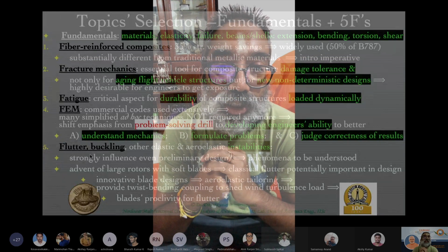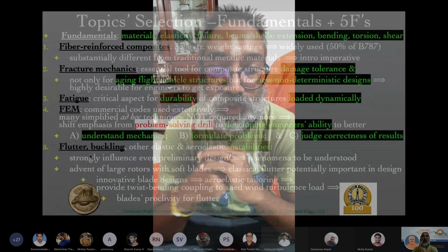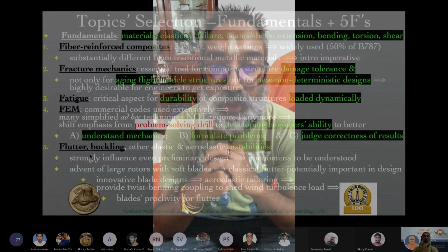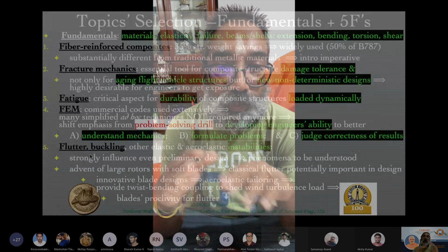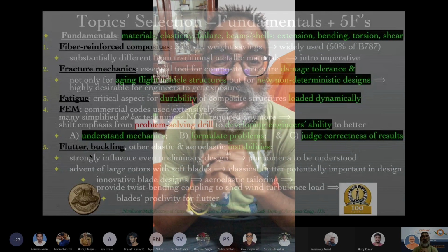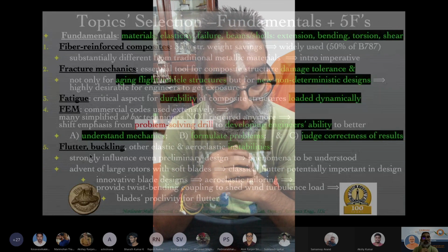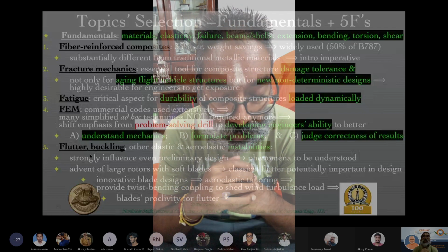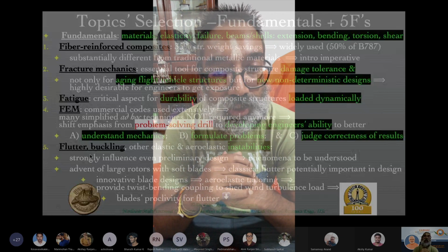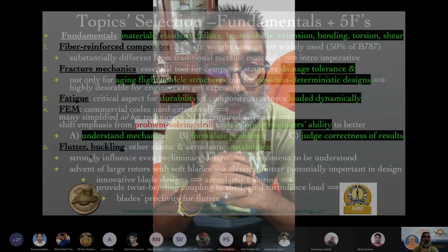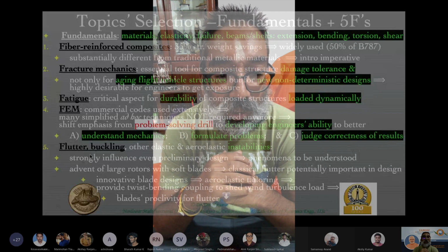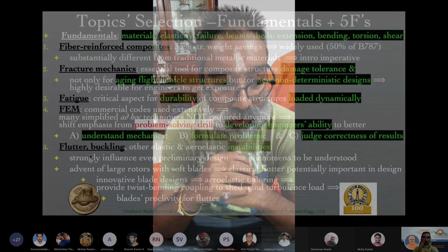This is what is called aeroelastic tailoring. You tailor the geometry of the composite layups in order to arrive at something which is much more efficient. In fact, we do this not only for aeroelastic tailoring, but tailoring in general for strength and stiffness as well, as we shall see when we deal with fiber reinforced composites.